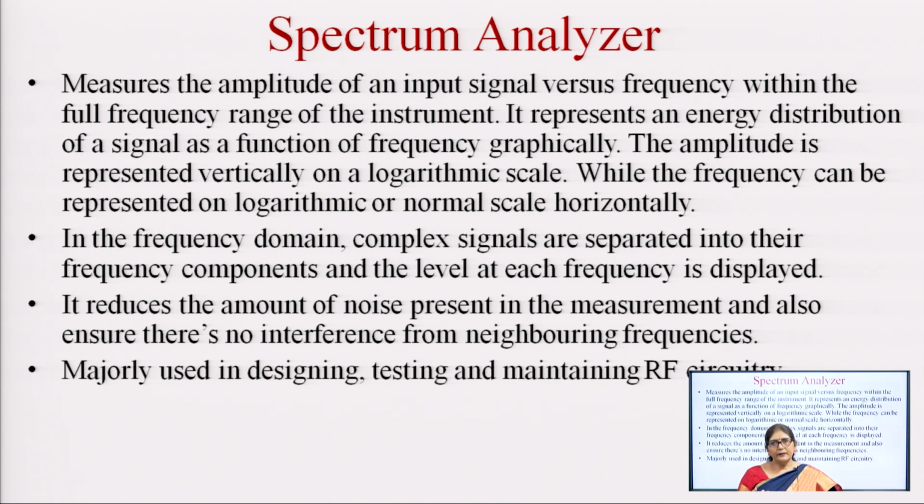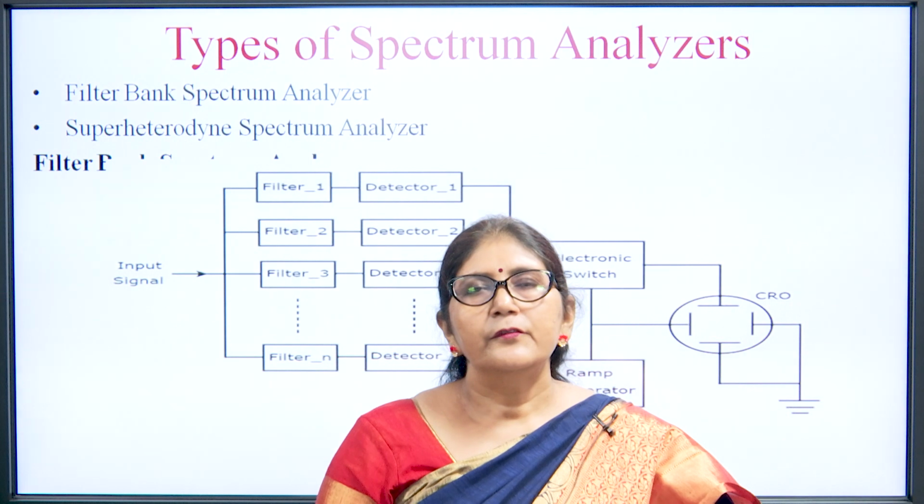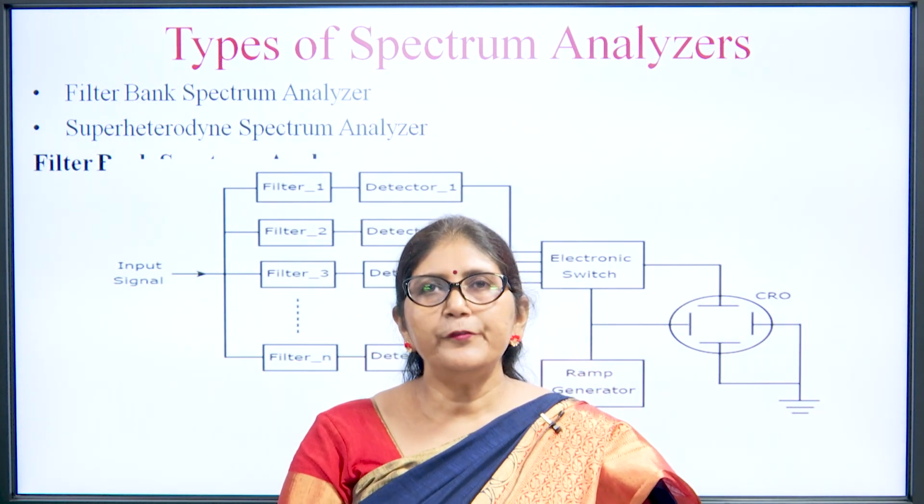In frequency domain analysis, complex signals are separated into their frequency components and the level of each frequency can be displayed. It reduces the amount of noise present in the signal, and this spectrum analyzer is very much used in the designing, implementation, testing and maintenance of RF circuits like wireless circuits and other circuits, the microwave circuits. These spectrum analyzers are used to analyze if there is any fault or any problem. Now we will discuss the types of spectrum analyzer.